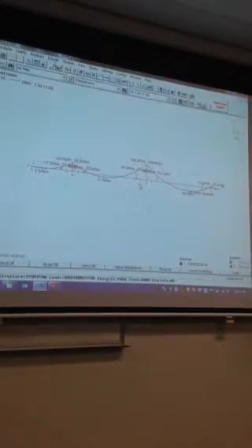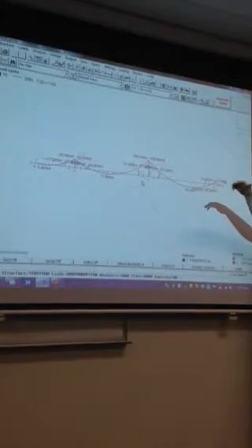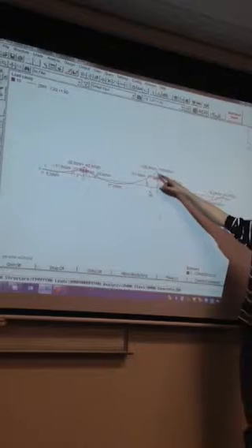But you might have different areas still here. So you can have different reinforcement. They might both be N12 bars, but you can change the spacing on the bottom. So the spacing on the bottom reinforcement, because that's a smaller bending moment here, might be N12s at 250 centres or something like that. But for the negative reinforcement, you'd always expect a little bit more. But you can still use N12s, you just close up the spacing. So it might be N12s at 150 centres, for example. So the closer the spacing, the more steel you have per square metre.